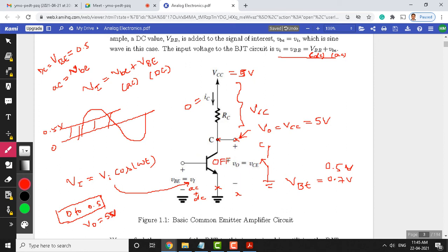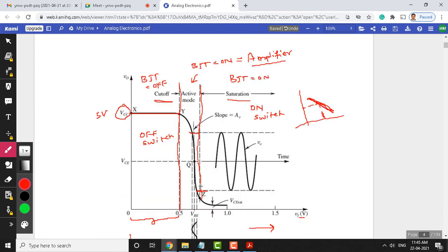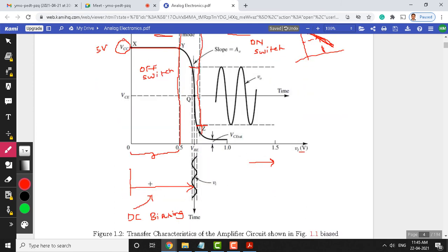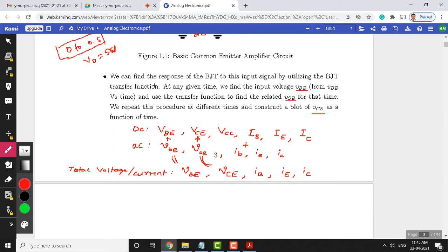Let us assume that this transistor is operating in the active region. Now, what will it do? It will do linear amplification, right. As per these characteristics you can see here, if you are operating here and you apply DC to elevate this AC signal to the active region, and once this sinusoidal signal is applied in the linear or active region, the transistor amplifies it to the maximum extent, and you can see the amplified signal here. That will show while explaining this output voltage.